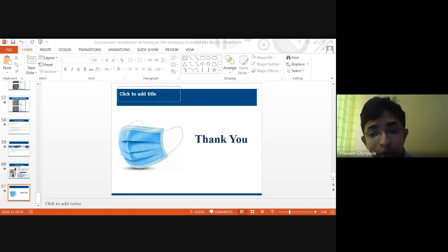So this is another combination where the problem of environment is there with the foundry, and a lot of people are working on how to utilize this waste foundry sand, and structural people are there. Physically you will blend it, I know that many people are doing 10%, 20%. What is exactly happening from that? Because this sand which you are blending might have some chemicals attached to it in a foundry, how those chemicals react and all. So this is a part. Then how the leachate characteristics will be there. This is the environment part, how it will affect if something comes out of it. What are those chemicals which are dangerous from an environment point of view, and how is it going to react in the concrete part.